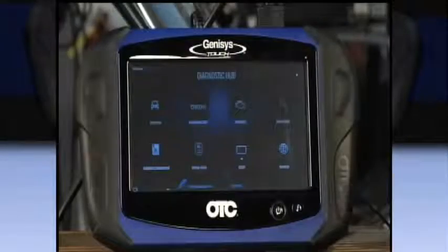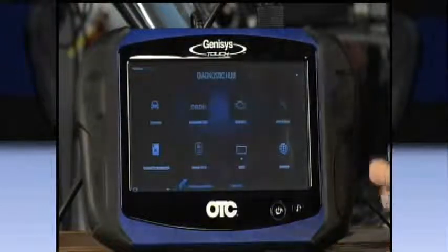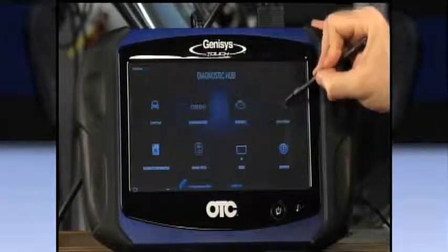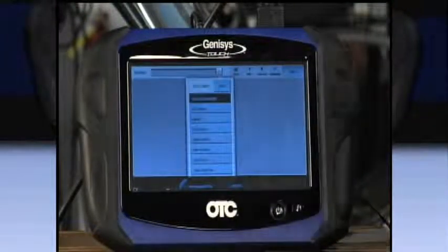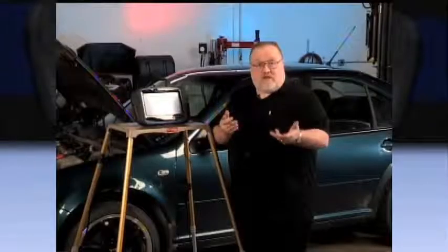So in our test procedures, it talked about going into vehicle data stream and looking at some specific vehicle data blocks. So I'm going to go ahead and do that simply by touching on the data stream icon. And now I have my data stream selection screen on the scan tool. What I can do is go in and look at specific systems. I can go into engine, I can go into knock control, I can go into various systems like that.